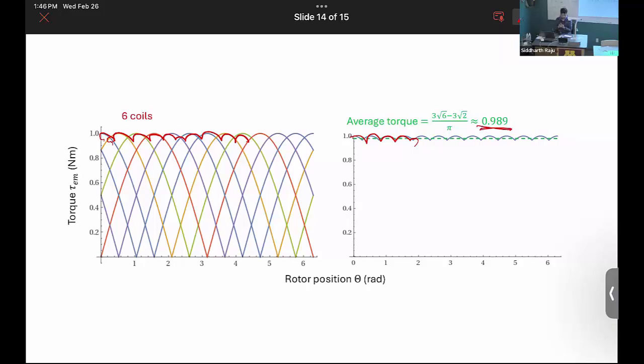But the problem is then you would have to put some amount of current for the rotor to start rotating. To avoid that, you skew it, so that on average, no point is closer to the iron than any other point, right? So that skewing is a little bit more complicated topic. We'll address it, but that's the idea, the 2 reasons why we do it, right? Anybody else, any other questions?